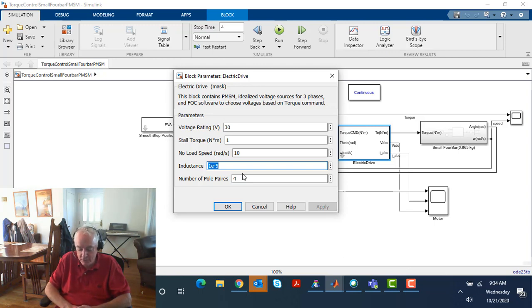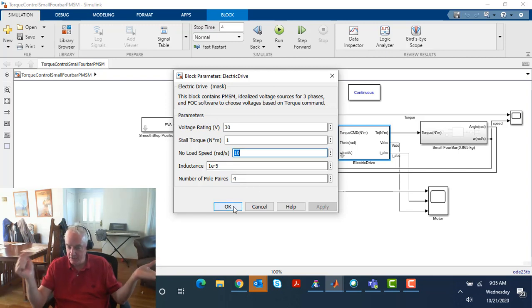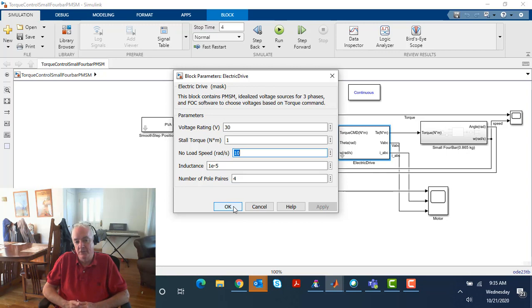Okay, so anyways, I think we're covered pretty well, and certainly, we use those numbers. We said, oh, okay, 0.3 on torque. Well, I think a value of 1 should be good enough, and a no load speed of 4 times our maximum speed. That seems like it'll be good enough. And we hit run, and we saw that we did not get excessive voltages, we did not get excessive currents, and that in general, we came up with a system that worked.